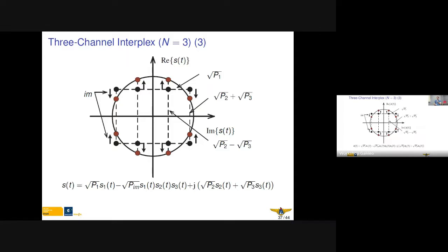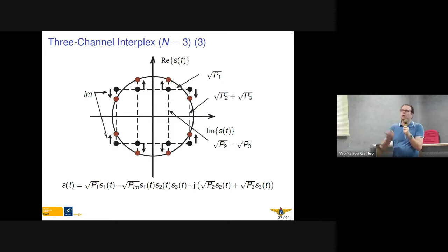And we could think about optimizing this, saying, what if we tolerate some clipping or some distortion of the signal, and not waste this power. This is something that is also discussed in the literature right now for GNSS, looking at the distortion level of the signals and reducing the power used for the intermodulation product.